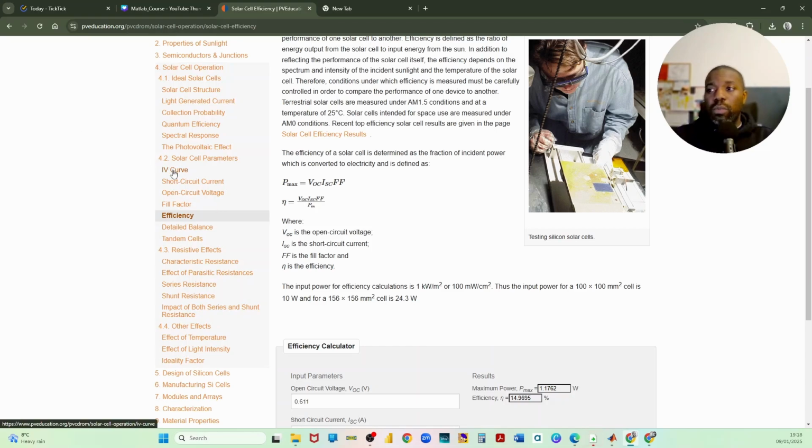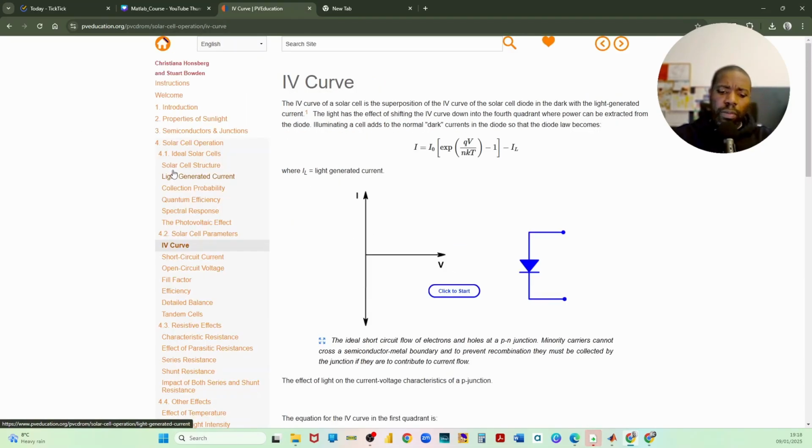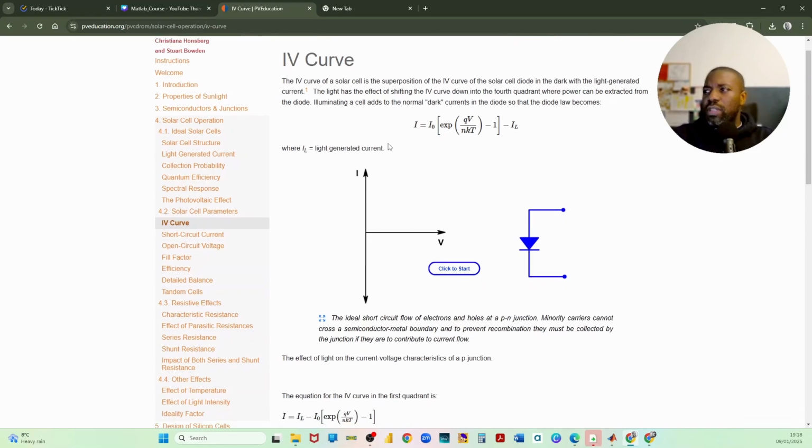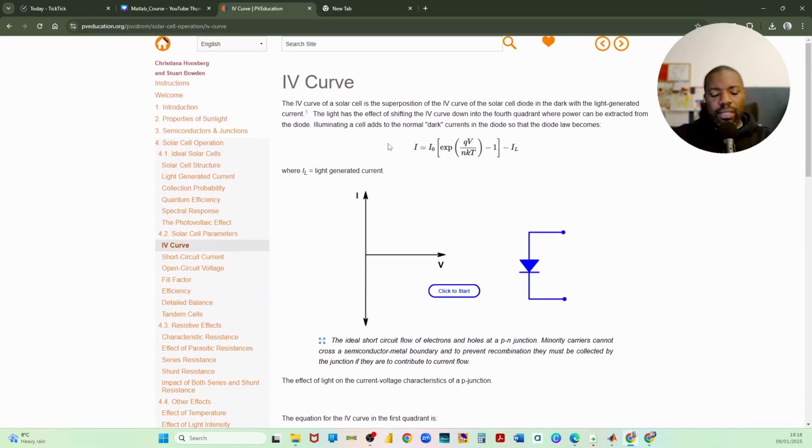And more importantly, when we talk about a solar panel, we talk about its current and voltage curve. Now, it gets a bit in depth here, but the only thing that I wanted to mention very briefly is that the solar panel, like I mentioned in the intro, has a light generating current, and then there's a diode that allows us to harvest that light generation current through having a potential difference between positive and negative, and that gives us the voltage. And with that voltage, of course, we are able to then charge a battery, for example.